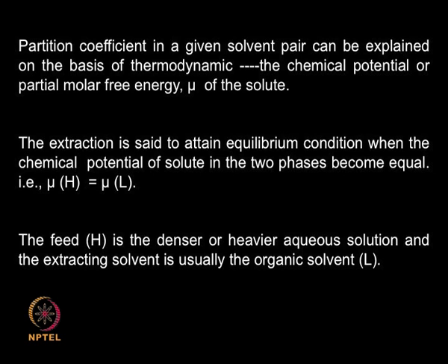Another important point we assume is that, for notational purposes, we call the feed the denser or heavier phase and the solvent the lighter phase, but it does not matter. Sometimes solvents can be very heavy, like chloroform, but generally we assume this for these sorts of explanation purposes. So in a thermodynamic situation where the chemical potentials are equal, the system has reached equilibrium.